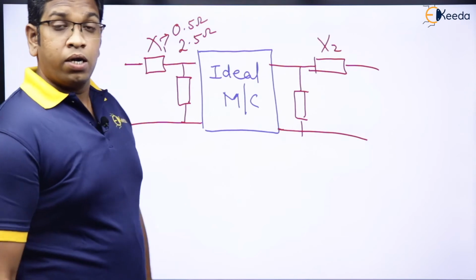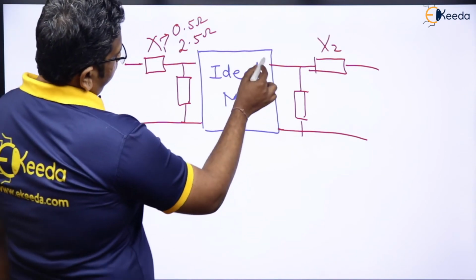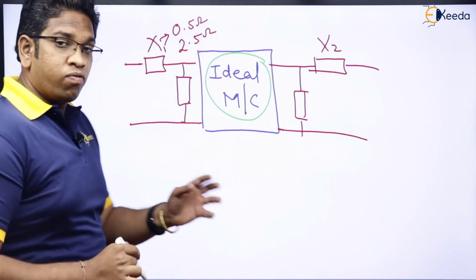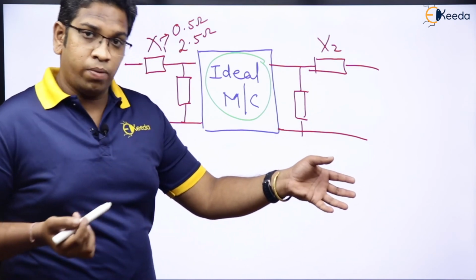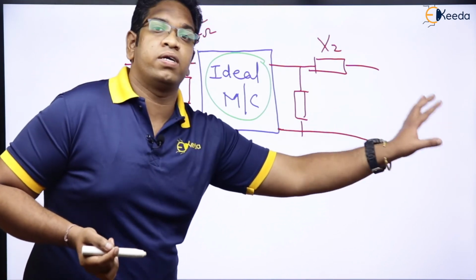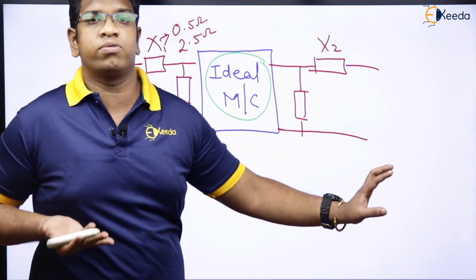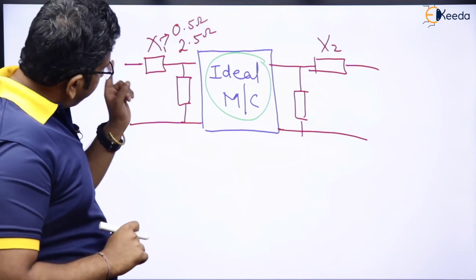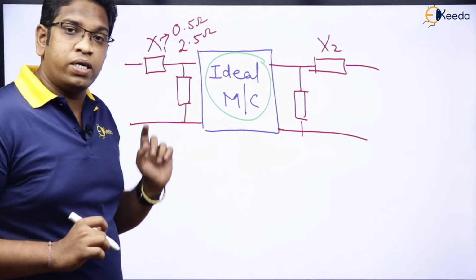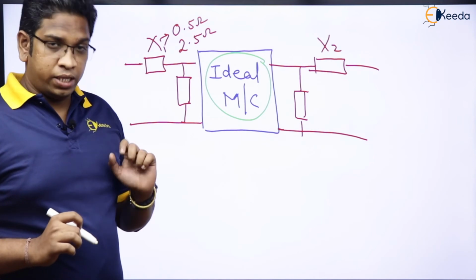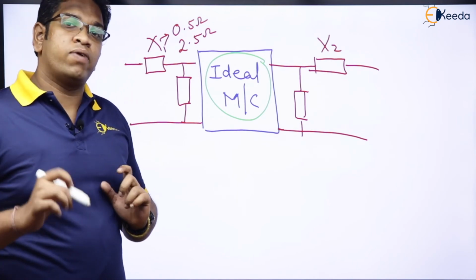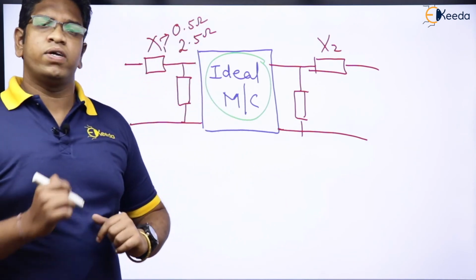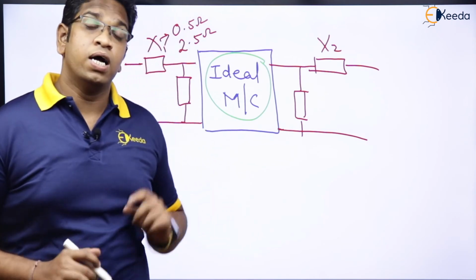See here. What I will do from here to here is the ideal machine analysis, which will be done in stage 1. In stage 2, we will be finding what parameters I need to show on paper so as to represent what is there in the physical machine. For example, leakage is shown in terms of inductance. That we know. Now, in stage 3, we try to find out the values of the reactances or the parameters. Then, in stage 4, we were going to find the performance characteristics. We know what characteristics we want. We know we need to find the efficiency, speed regulation, voltage regulation, etc. But how will you find them?